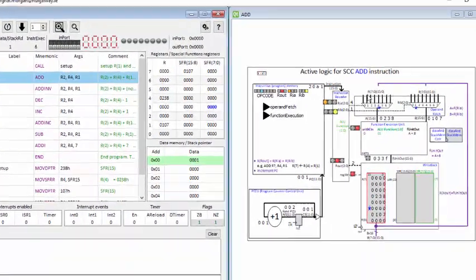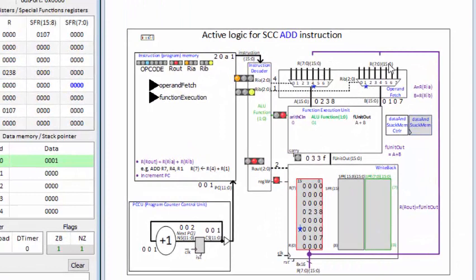The add instruction has two parameters, or two values coming in from the operand fetch, using RIA, this field, bits 5 to 3 in the instruction, defining register 4 as a source, and the value 238 is provided into the function execution unit. And RIB provides register 1 on bus B, 107, into the function execution unit.